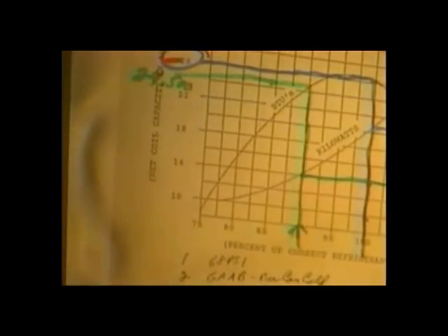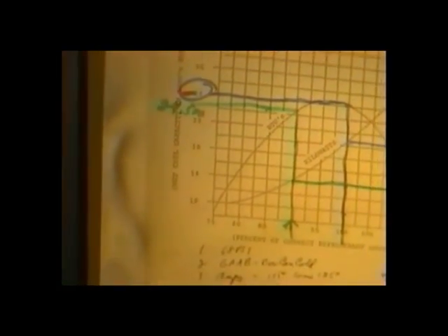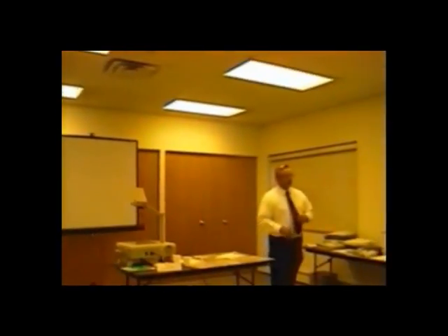We undercharged it by 10%, and look at how much cooling capacity we lost. Hardly anything. But look at the savings we have in electricity. And I've got to tell you, that's what contractors are doing today. I'm going to shut this off here a second. Let's talk about this. Contractors are absolutely doing this today.